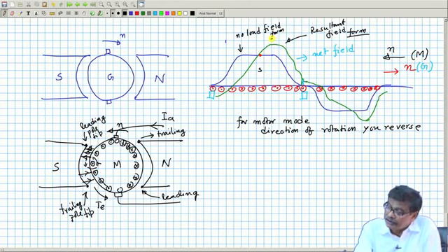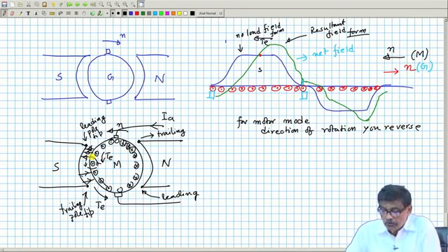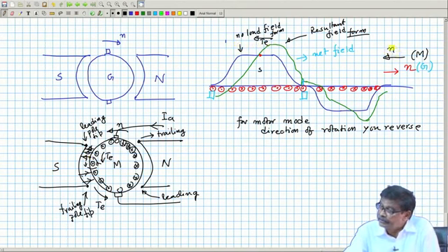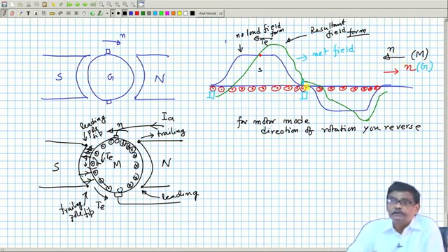That is why electromagnetic torque is in this direction, from higher concentration of B to lower concentration of B. Everything is consistent, and electromagnetic torque in whichever direction acts, in the same direction the armature moves. This must be understood. In one stroke you can say that.